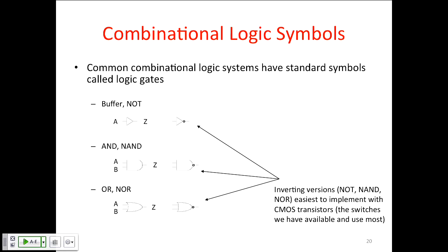So how do you take one of these gates, do you think, a NAND gate, and make it into an AND gate? You can use 2 NANDs. What's a cheaper way of doing it? A NOT gate, yeah. You can take a NAND gate and put a NOT gate on its output, and then you've got an AND gate, right?